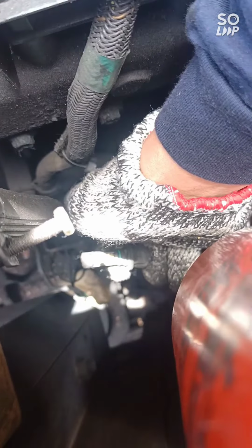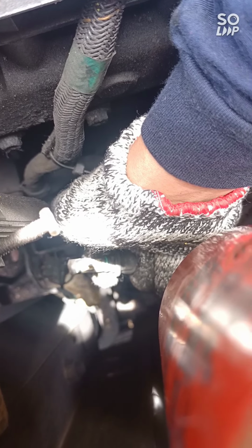As we can see, the wiring was crisp because of the punctured exhaust pipe. The gas from the exhaust pipe burnt the wires, so it is crisp. And as we can see here, we have a damaged engine speed sensor. That's why we have an engine speed sensor active code, which also triggers the engine shutdown.